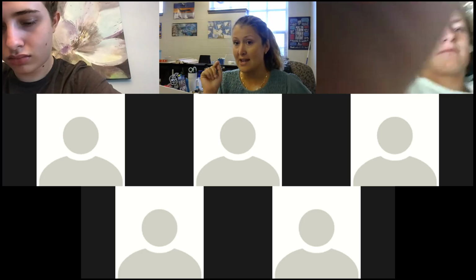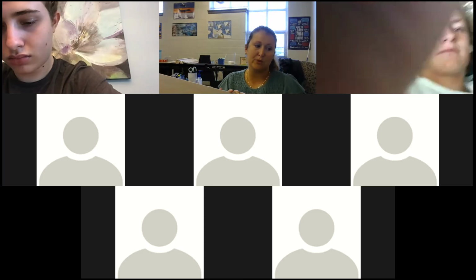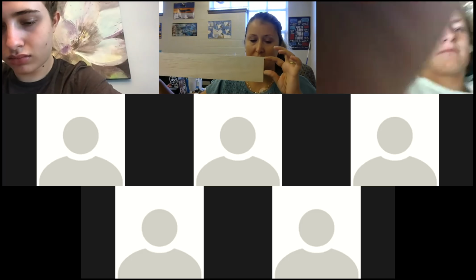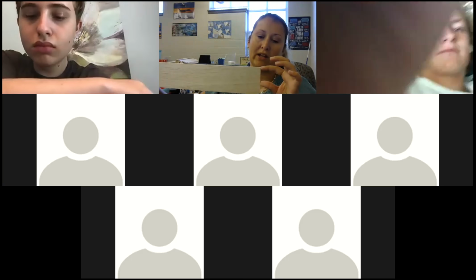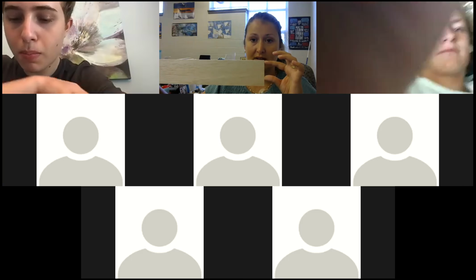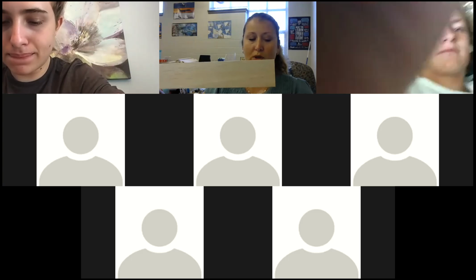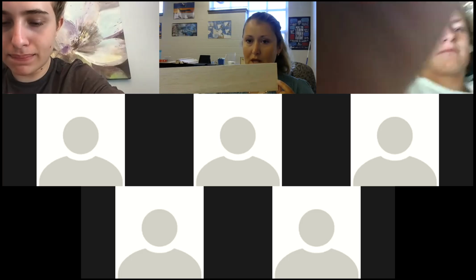Based off of the taper on page 2, please take a look at the camera. You will be able to see what is the chord of the wing at the very end. You're going to mark that point, and then you're going to connect the midpoints that you marked with the end point measurement. And then you have to cut out this piece.